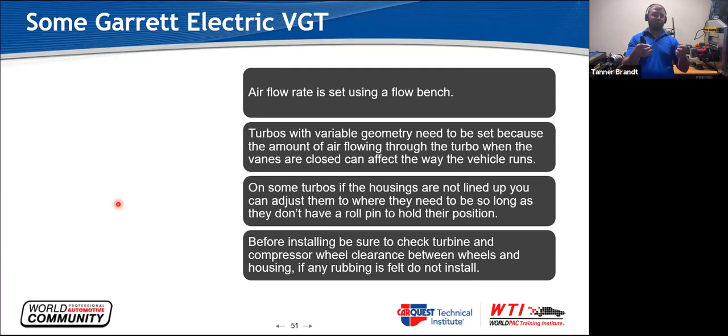So if it's had oil run through it, your axial and radial play in it is going to be pretty tight. You shouldn't be able to move it and touch the housing at all. If you get a turbo and it's dry, it's going to feel like you have a lot more movement in it. It still shouldn't be able to move enough to touch the housing. If it moves enough to touch the housing, that turbo is not built correctly, and it needs to be sent back. So don't install. I want you to grab it, move it this way, move it this way, move it up, move it down. Make sure that it doesn't hit the housing.